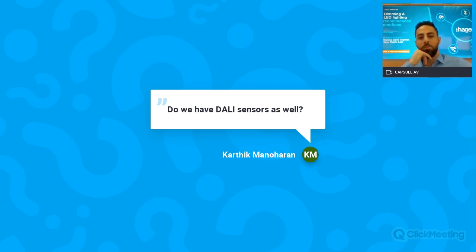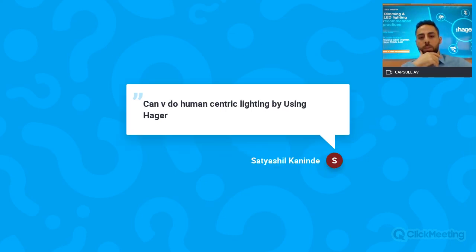We have DALI sensors. In Hager, we have one presence detector. I'm not sure if you are speaking of a sensor as a presence detector or a motion detector. We have a presence detector which can control DALI directly, without going through a dimmer. You put a ceiling-mounted presence detector and connect it by DALI. It has DALI terminals. You connect it to the DALI devices, and it can control, I think, up to 20 or 24. I'm not sure. So you'll have constant light control, or constant regulation.